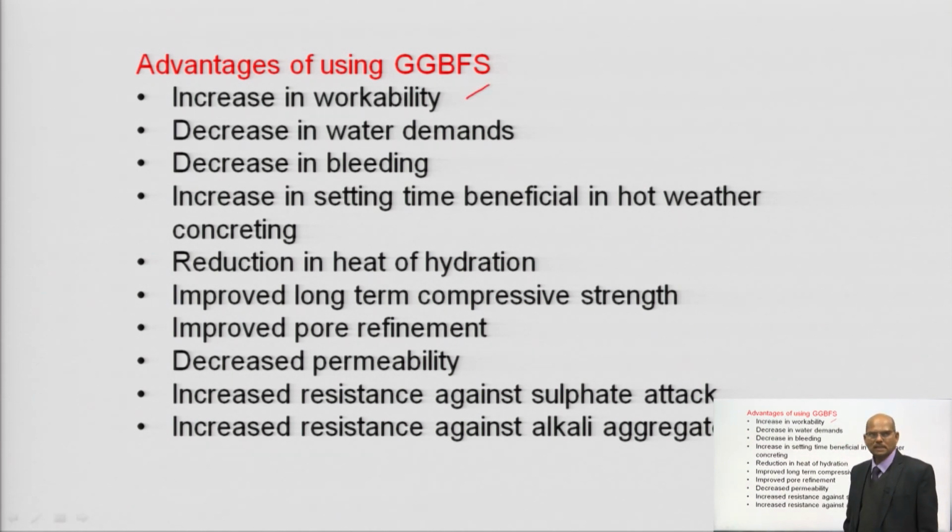Although the particles are angular in nature, if you do a microscopic study of GGBFS, their size is very fine, but that is not going to affect it, even though it is angular in nature. And if you see the particle shape of fly ash, that is spherical in nature. So, that gives better workability than GGBFS, but still here also you get improved workability.